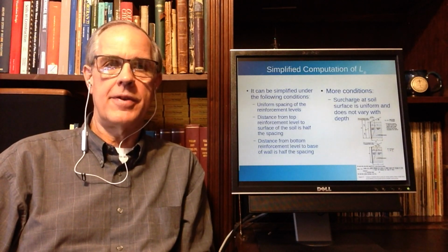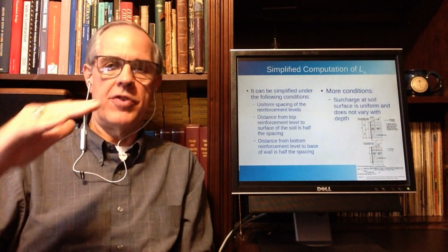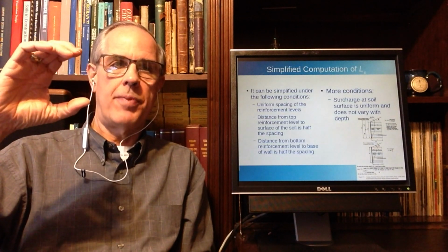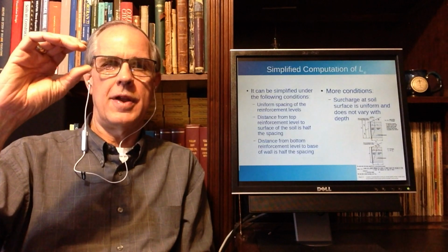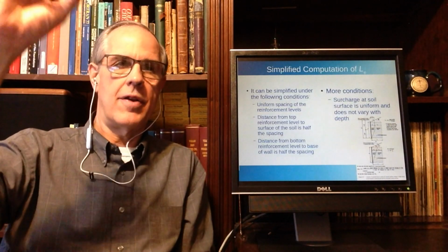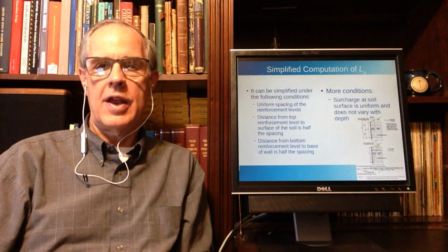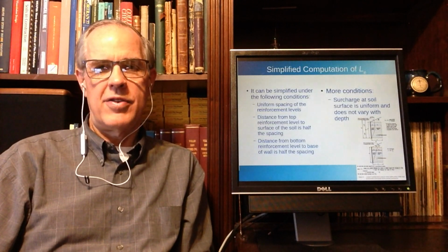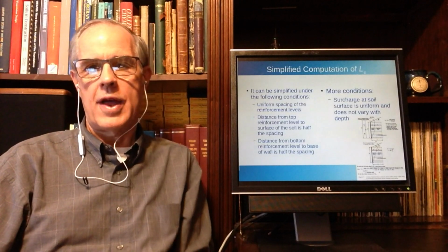If the geogrid spacing is, say, 750 millimeters, we can pretty much assume that the panel spacing will be 375 on one side and on the other, on average. That is, the geogrid connection to the panel is going to be in the middle. That's not necessarily absolutely the case, but we're going to talk that way.